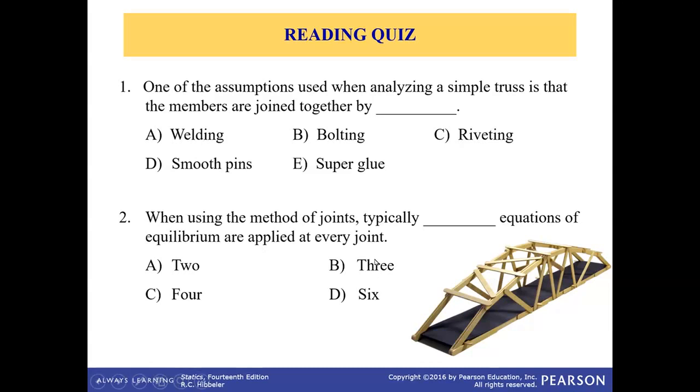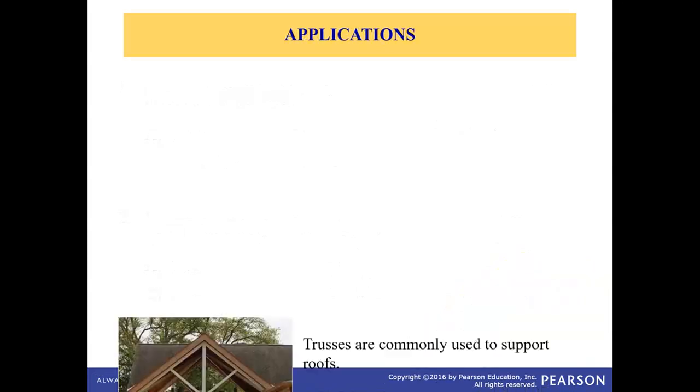So our objective to solve the problem of trusses is that we have been given a structure like a truss and the externally applied load at the truss joints, and based on those loads we would like to calculate the loads in each member of the truss, and then we would like to make sure that the design of the truss is safe such that each and every member has the load within the member which is within the limits of the tensile or compressive strength of that member. And this is what we are going to do in this chapter.